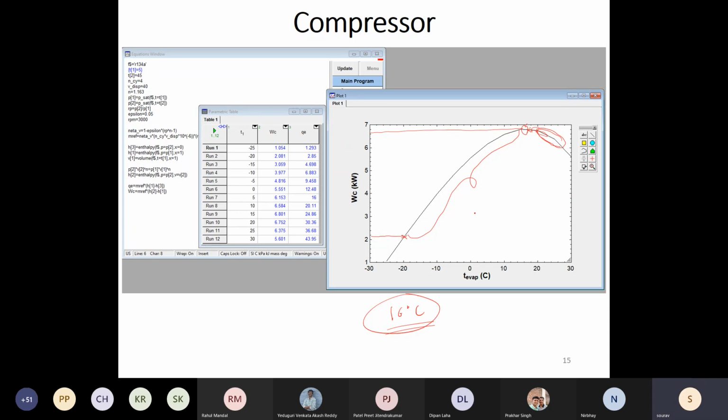It is not going to harm your refrigerator as such, even if you operate it continuously for those days. And nowadays we use stabilizers in case of power cuts and power spikes, so not an issue. Rather, if you turn it off for several days and turn it on again, then it creates an issue. It demands a lot of power from the motor to pull down the temperature.